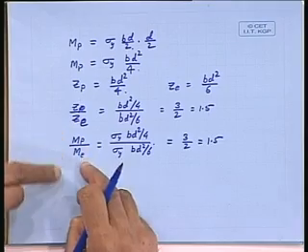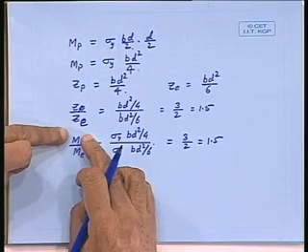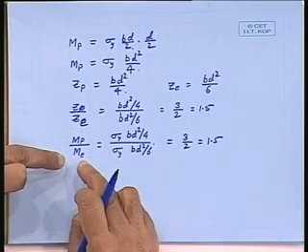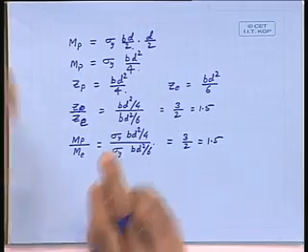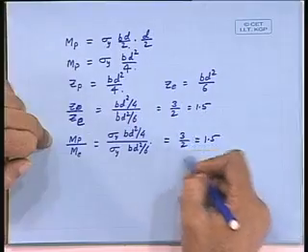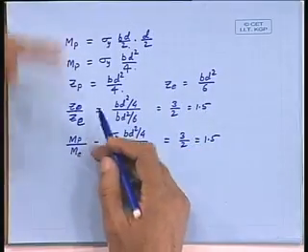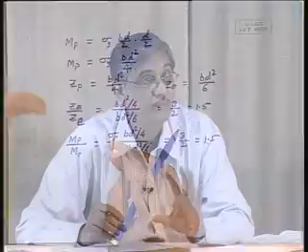So if you take the ratio of plastic moment to the moment when the extreme fibers become just yield point stress and the entire cross section is elastic, this ratio is same as the ratio of the corresponding section moduli defined in the plastic condition and the elastic condition.